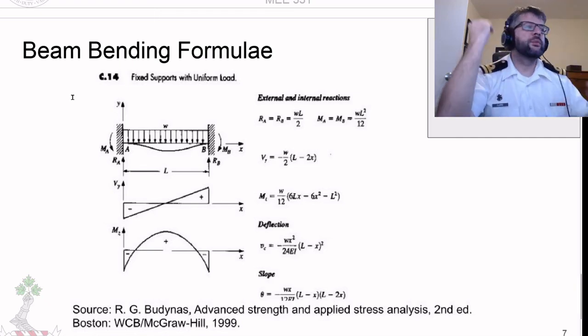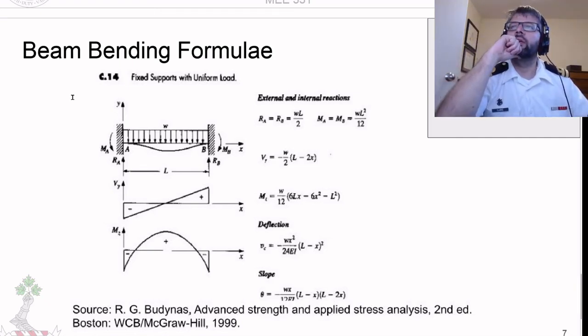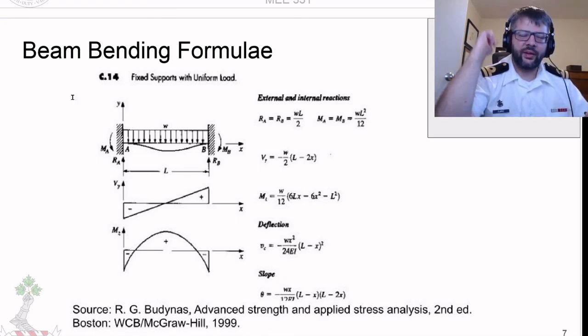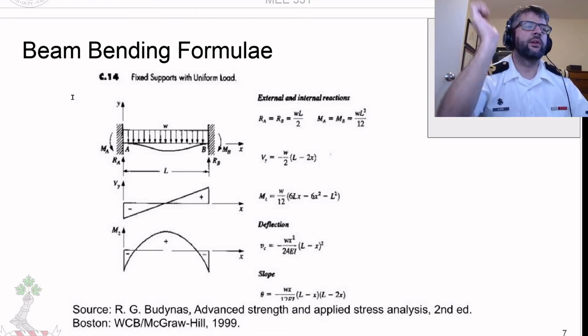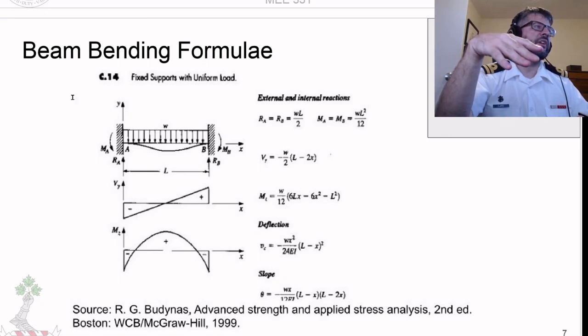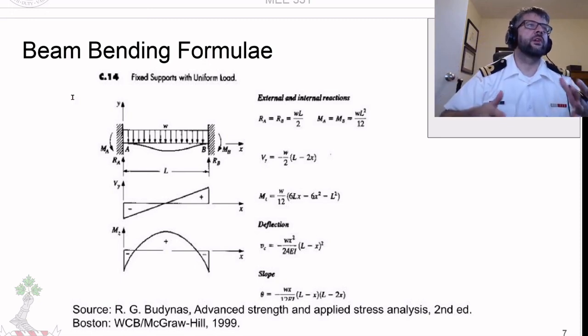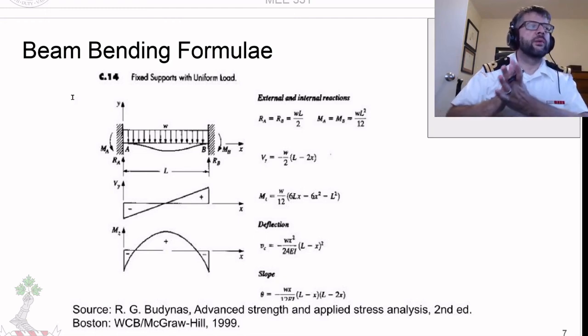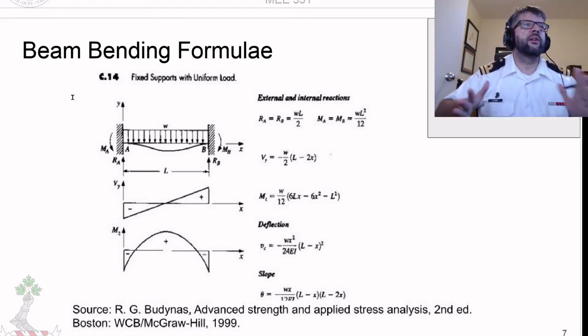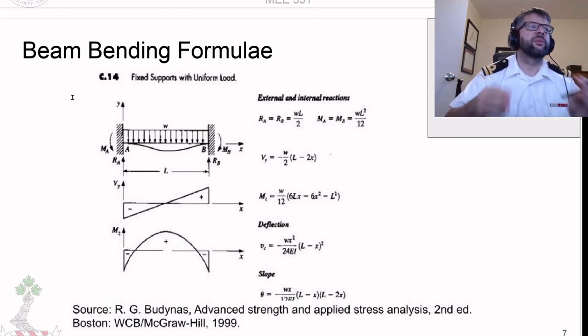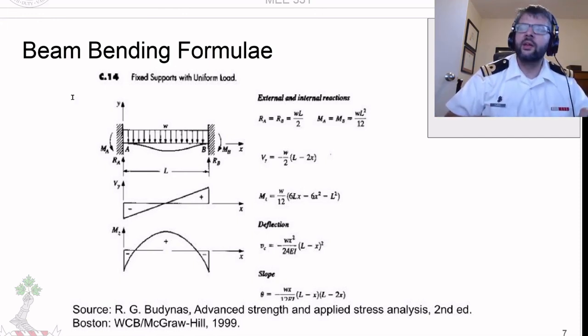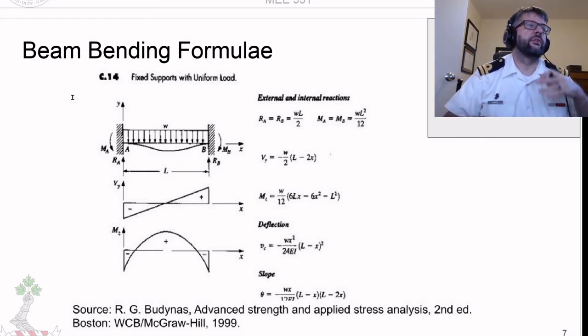So yeah, when it comes to solving your indeterminate problems, again, cannot reiterate this enough. You just need to find a good compatibility condition, state it, set up your system of equations, and the compatibility conditions are going to be what allows you to relate the various unknowns that you otherwise wouldn't be able to solve for in a manner that reduces the problem to something that's solvable. So that's it in general, and we'll go through a few examples.